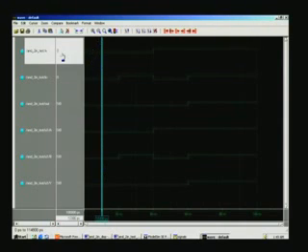So let us see, this is on the design, test bench as such, A, B and out. This is the A waveform, and here it is 0 nanosecond, and 20 nanosecond is marked here, 40 here, 60, 80, and so on. As per the test bench, every 20 nanosecond we are changing the inputs. For example, right at 0 point of time, we have 0, 0. You can see here, this is 0 for A, and for B it is 0. Similarly, for A and B also, you can see that as 0 here.